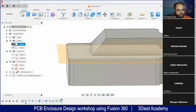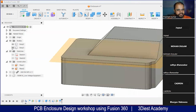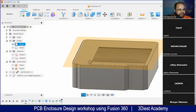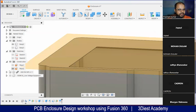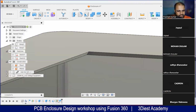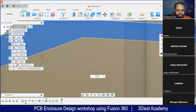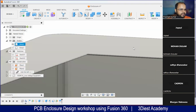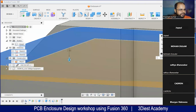Now if I turn off the body 2, you can see this is my body 1. And if I turn on my body 1, here you can see we had to bring down this plane a little bit, by a small distance. So we'll go on to the design history and we'll click on the edit feature. We'll make it 2.4 or maybe 2.8. Let's just edit this one and write 2.8 and we'll press OK.